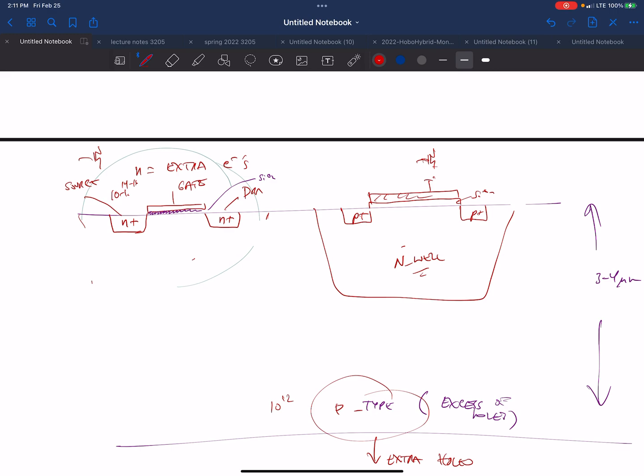So why didn't germanium succeed? The first transistors were actually germanium. Why didn't they succeed? Why did silicon dioxide succeed? I cannot tell you how much work went into gallium arsenide, especially in the 80s and 90s, because the mobility of gallium arsenide, the velocity of electron holes, is much higher than in silicon. So the idea is we're going to get really fast transistors. The reason it didn't work is because of not just silicon, but silicon dioxide.